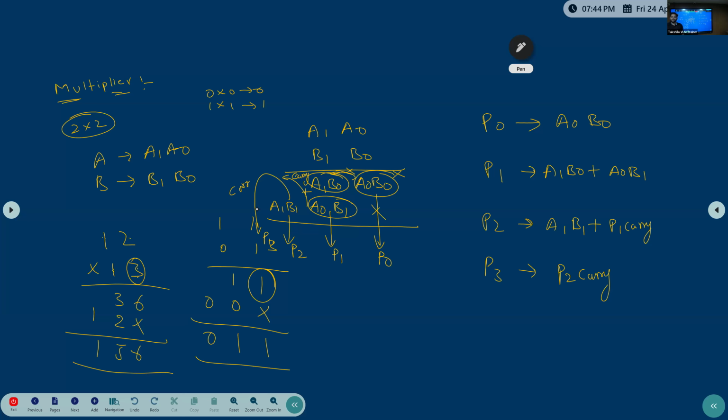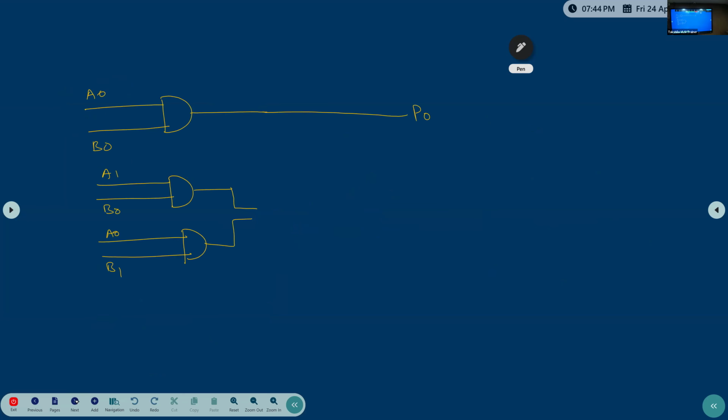In binary addition, for adding 2 bits, what circuit will we use? This is one bit, this is one bit. These are two binary bits I am adding. What do I need to use? Half adder. Two binary bits we are adding, so we need to use a half adder, not an OR gate. This is the trap. Remember, note down this point.